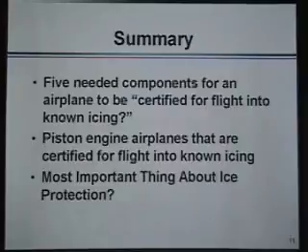Let's see. Number 4, you're going to need dual, that is at least two separate pitot-static systems. In fact, I've seen transport category jets with three separate pitot-static systems. So for instance, you're flying along in your Cessna 421, it's a big eight-passenger turbocharged pressurized Cessna, and one of your pitot heat systems fails, then you still have a separate pitot-static system to give you good airspeed indication.